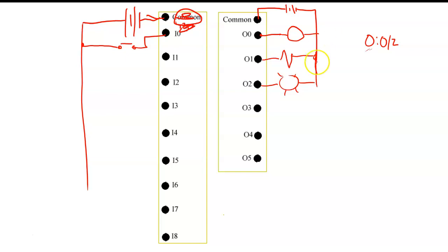So are these in parallel? Well, no, they're not in parallel, because if they're in parallel, both sides would be connected together. I see students do that all the time. They'll come in, they'll see 5 resistors, or just let's say 1 resistor, and they're connected on this side, and this side's not connected, and I'll say, are they in parallel? They say, oh, they're in parallel. But to be in parallel, both sides have to be connected together, right?